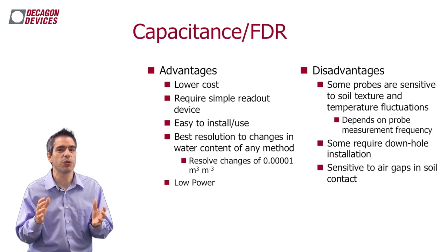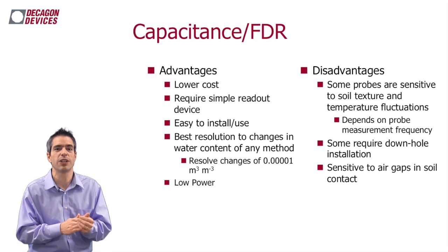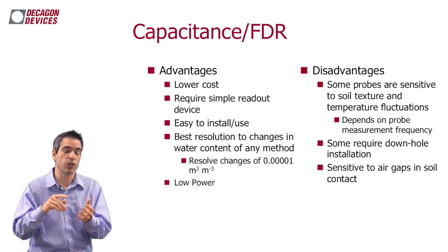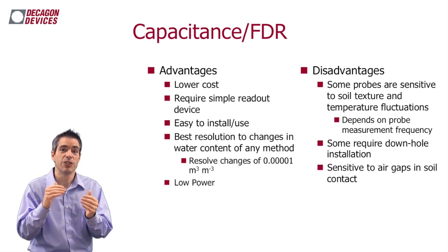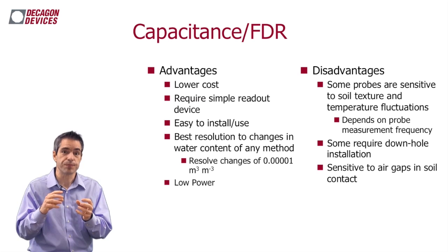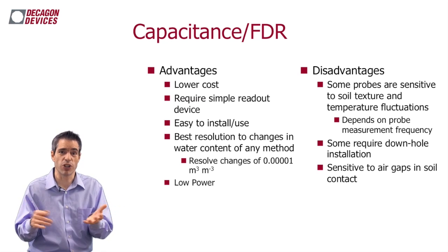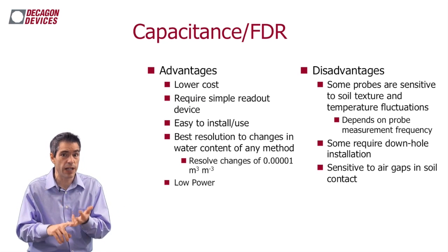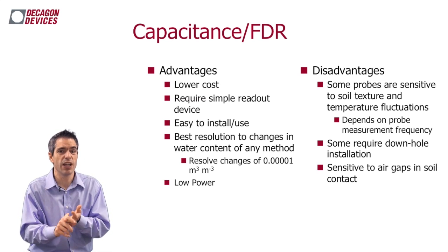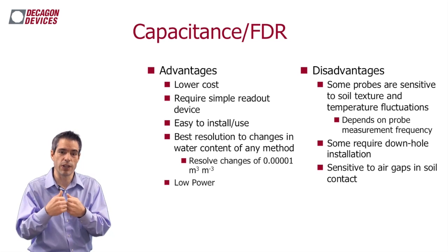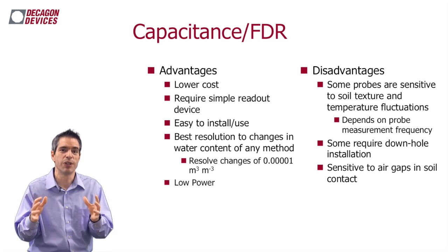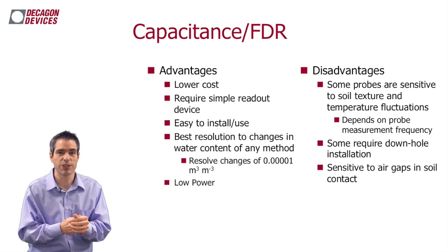Well, it wasn't quite so easy, because these measurements were turning that electromagnetic field on and off so slowly that other things were storing the charge, not only the water. You can imagine that salts in the soil would store that charge, and of course charged surfaces on the soil, the way they interact with water, would also change the charge storage measured by some of these instruments.